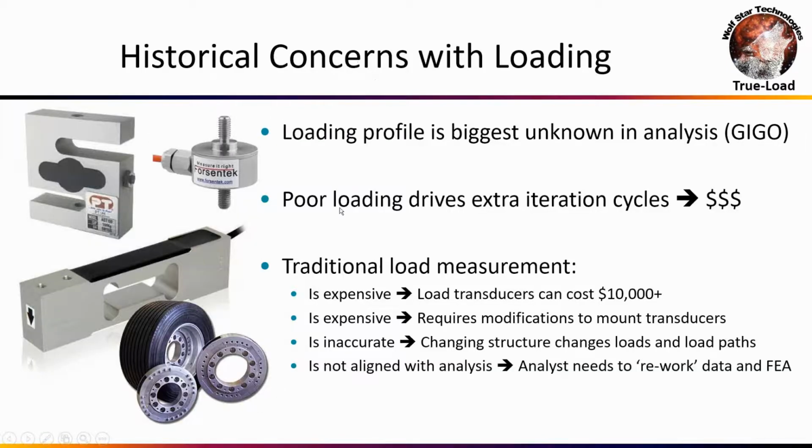So, historical concerns with loading. You can have a perfect FEA model, perfect CAD model, perfect mesh, perfect solver, but oftentimes when an analyst goes to use their FEA model, when they go to throw it in for the solve, they'll guess at what the load case is. And if you're guessing at what the load case is, you're basically guessing at the results. So in the US, we've got a term that we call GIGO, garbage in, garbage out. So if you're just guessing on the inputs, you're guessing at the outputs.